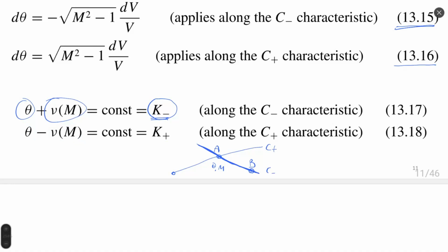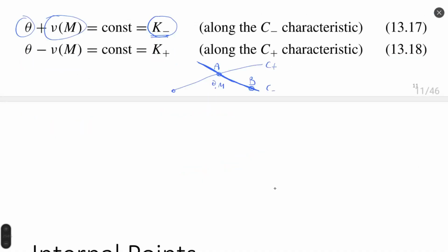Let's have one simple calculation. We have space for this calculation. Let's assume that this would be negative direction of flow. Let's assume that my theta is, it's not a mistake, minus 10 degrees at point A, and my Mach number is 2, also at point A. I need to know the Prandtl-Meyer function at this point A as a function of Mach number. I will need to go to appendix C, probably, and calculate. Just a moment, I will try to open this appendix because it's on the same computer.